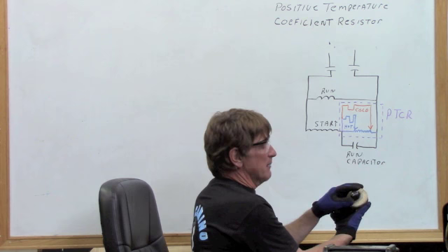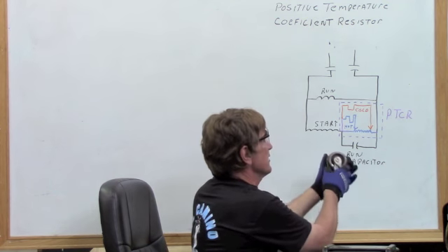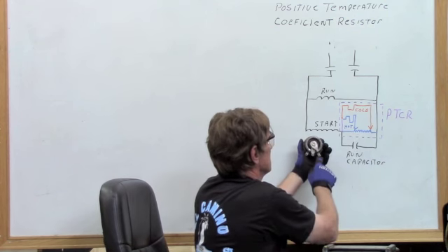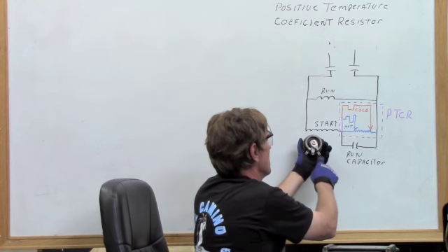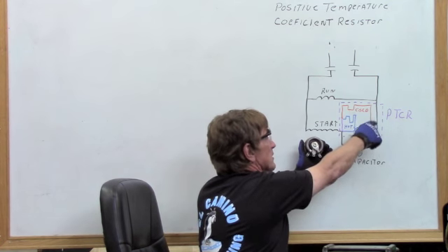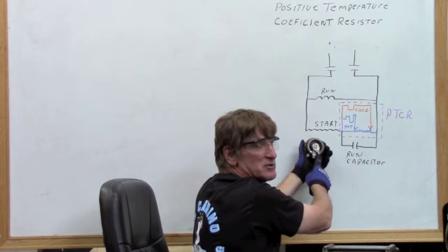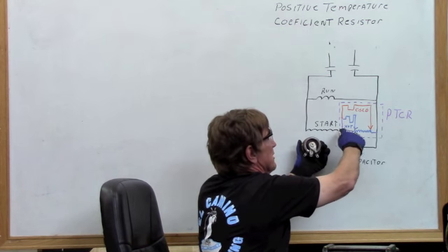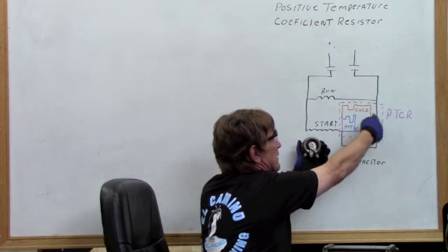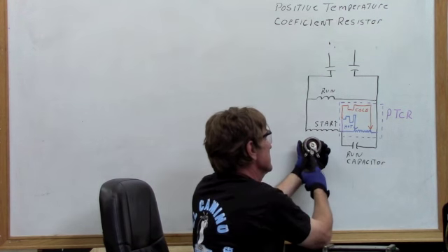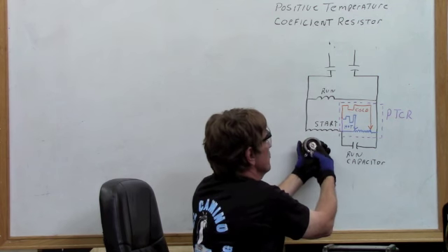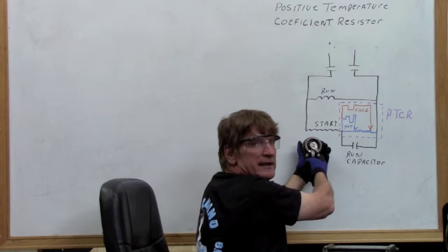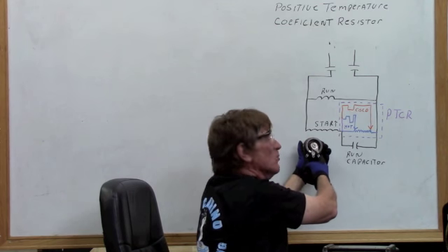On my potentiometer, I'm manually turning this, and what I do is I have leads here, which represent these leads here. This wiper that represents here is this wiper represented here. When I go to start, the current's going to pass through here, through the start winding, through here, to where there's very little resistance, basically going straight from here, through the wiper, and over here to my other lead to power up that start winding.